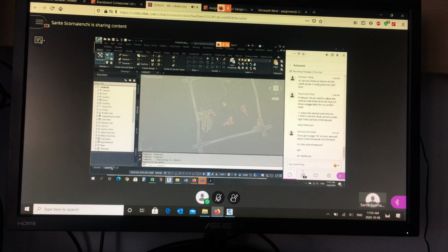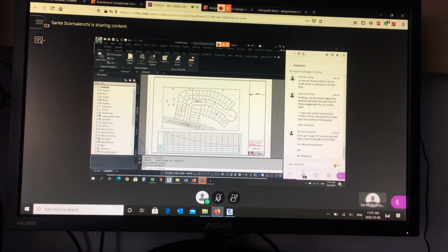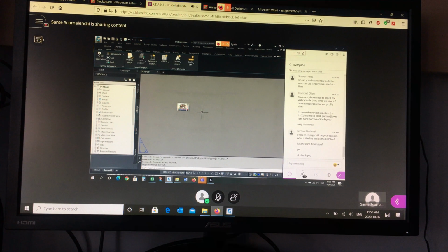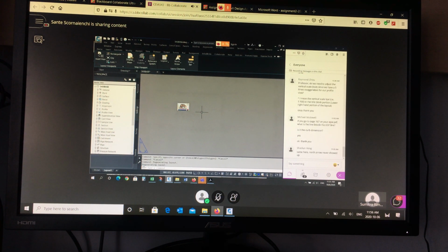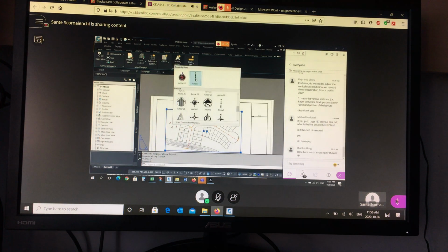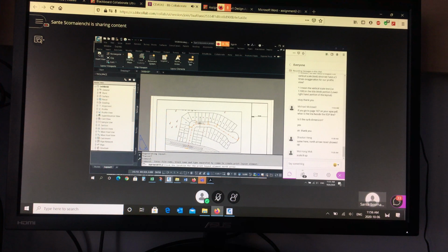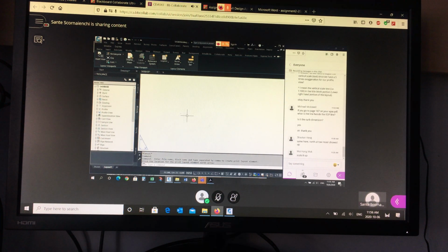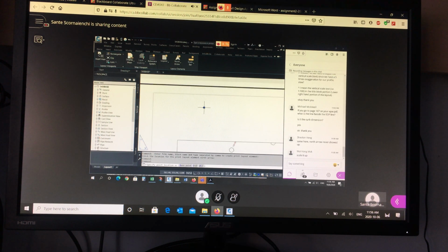Okay, so if you go to your paper space, zoom extents: Z, enter, E, enter. Does it do something like this? The north arrow never shows up. The same problem. Okay, it should show up on layer 0 by default. So let me put one in. I'm going to pick a spot. Don't assume 0, right? So pick a spot, click, and it's very, very small. So you need to click on it if you can find it, and then change the scale by stretching it.